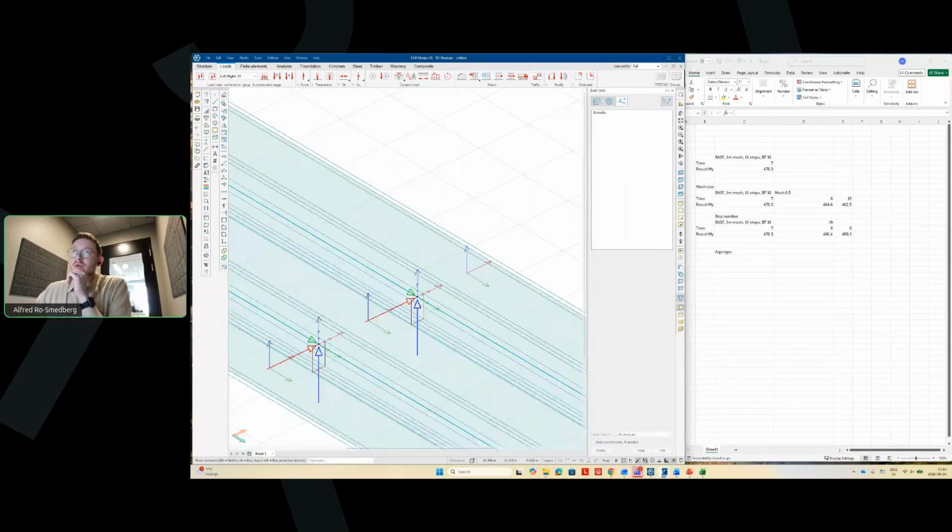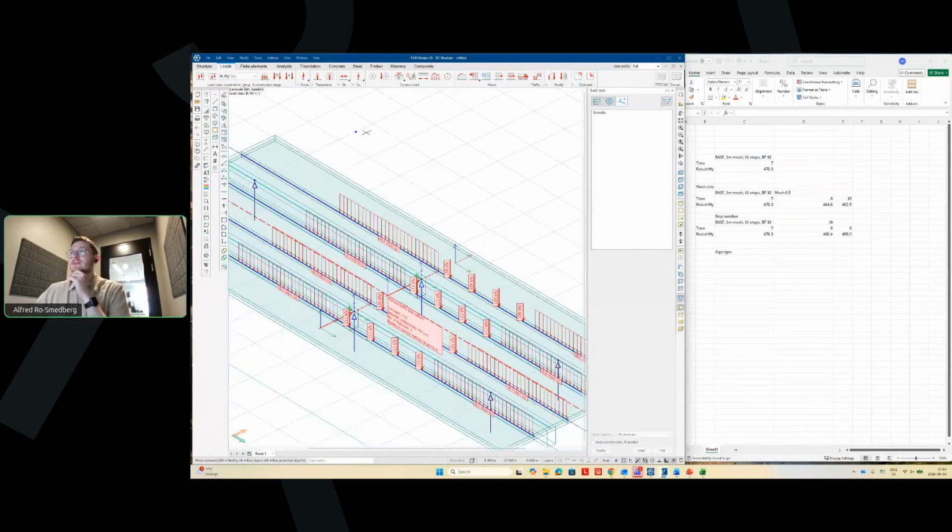So to change the algorithm options, the only way to access that is through the traffic load module button here in the loads. We use the question mark. Something to consider is that if you have selected the road vehicle traffic pattern here and you want to change a train vehicle, you're not able to access that load if you have the wrong type selected. So make sure that you select the right type that you're working with right now.